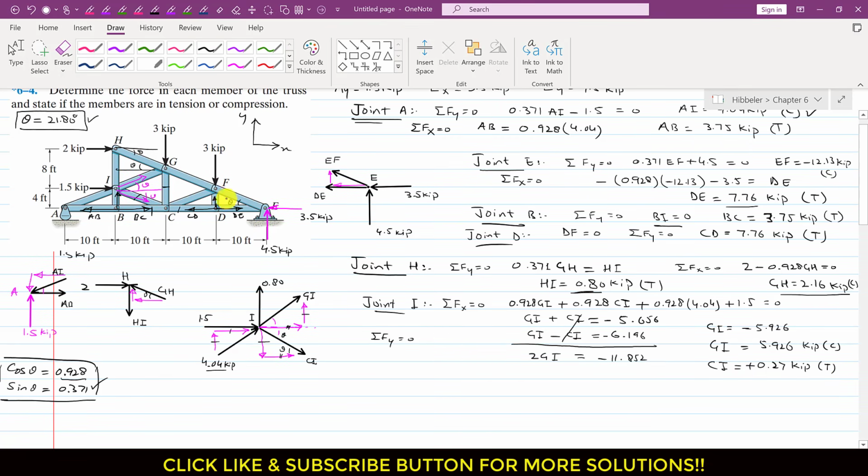Next, we are going to consider this joint F for equilibrium. Let me draw the forces at this joint F. As we know, this DF member force is 0, and we know the magnitude of this EF force. The EF force is a compressive force, so it will have a direction like this.